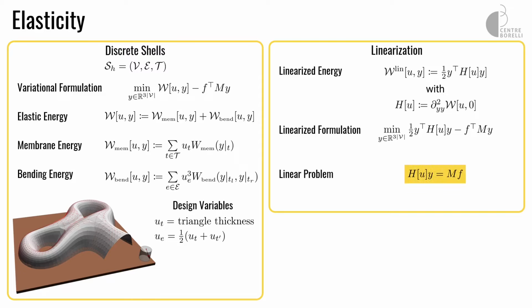So this is the important thing to remember for the rest. Elasticity in this first part is just Hooke's law. We have some system matrix, which depends on my thickness, my design parameters, and it relates my displacement to my forces.